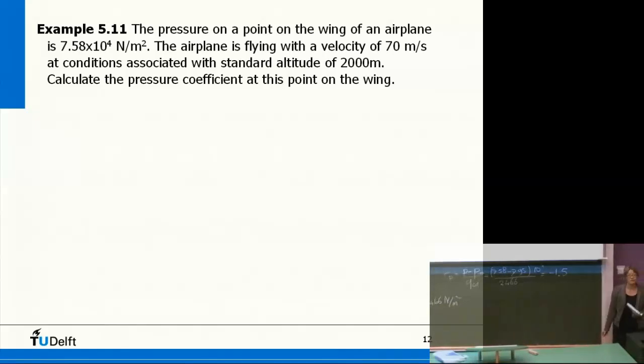Is this correct? Anything wrong? No, right? We should be worried if it's larger than 1. But as long as it's smaller than 1, it might be reasonable. So that's always a sanity check you can do on the pressure coefficient.